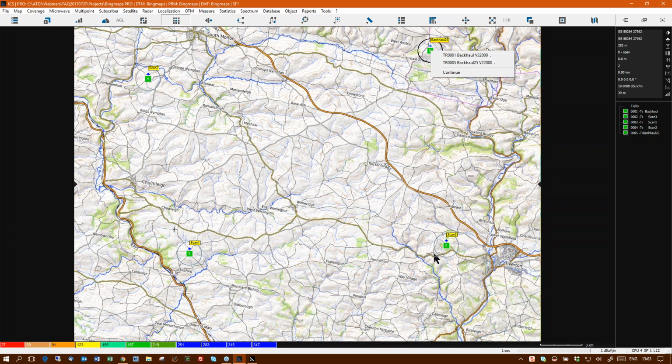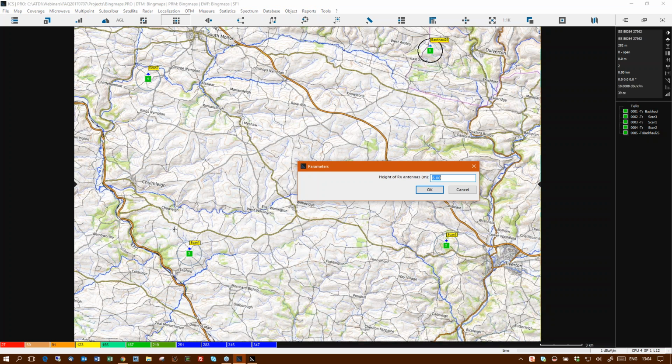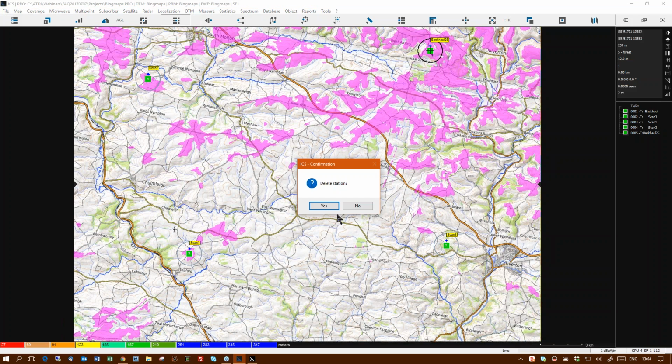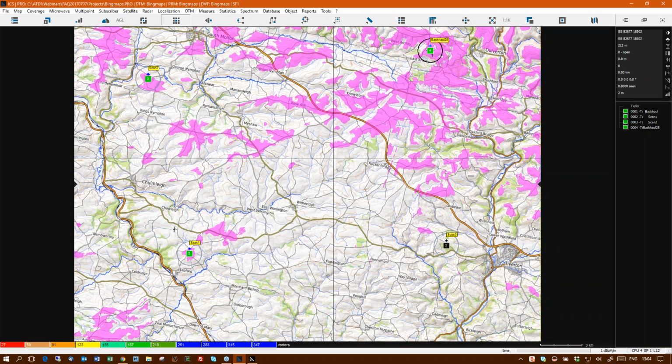First thing you do, get a feel for, you've got these 3 potential radio sites here that could be used to cover this area, and the idea is to first see whether or not any of those sites will actually see the base station up here. And again, the fastest way to do it is a visibility plot. All these sites have currently got 12-meter antennas, so we'll just do that. And you can see that that site can be seen, this site can be seen, that one can't. So goodbye. So that one's gone. So this is just a quick choose your radio site job.